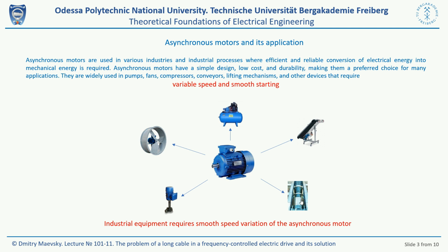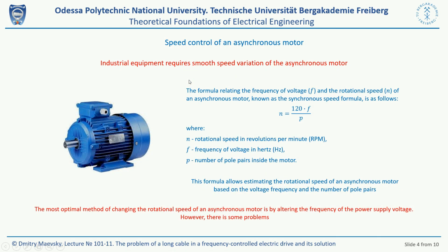Very often, as in the case of an elevator, for example, we need to control the rotation speed of such a motor. Indeed, the elevator must smoothly start moving, reach its maximum speed, and then smoothly come to a stop. And that's where the difficulty arises. The fact is that the only effective way to control the motor speed is to change the frequency of the voltage that is applied to it.